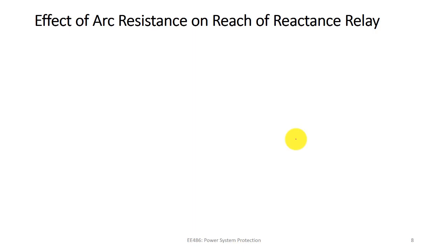Because it very well operates during the arcing fault. Because already we have seen, under arcing fault, your impedance relay doesn't operate properly. It has some underreach problem, right?